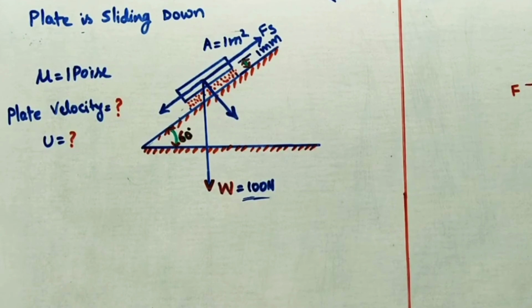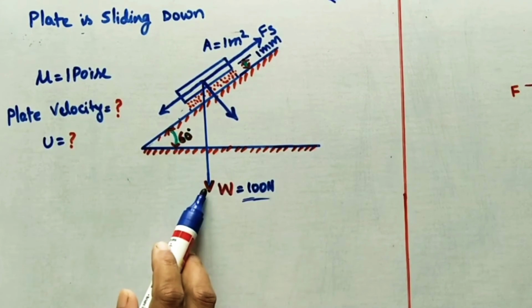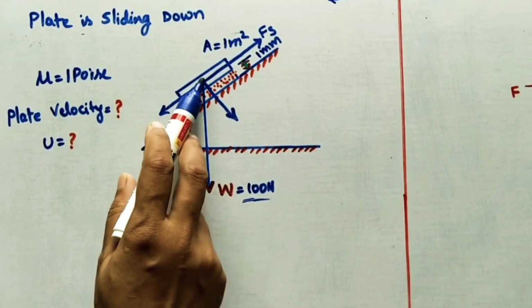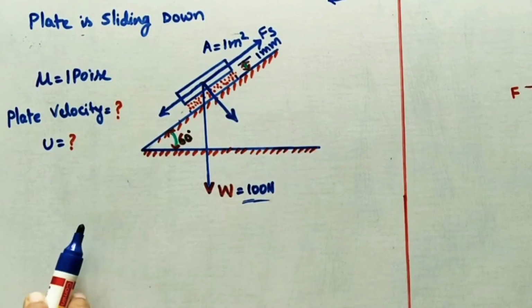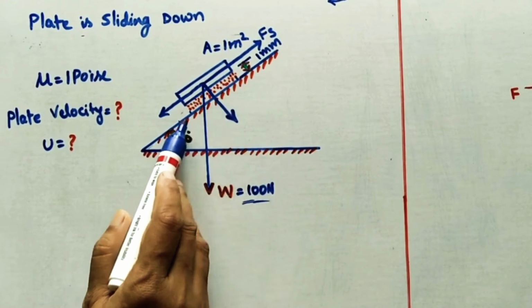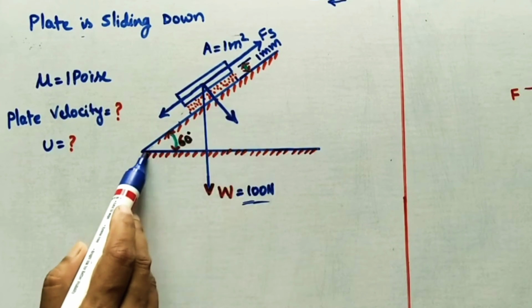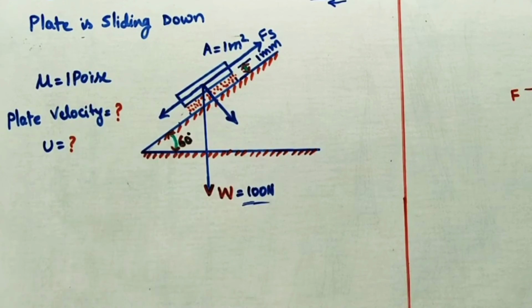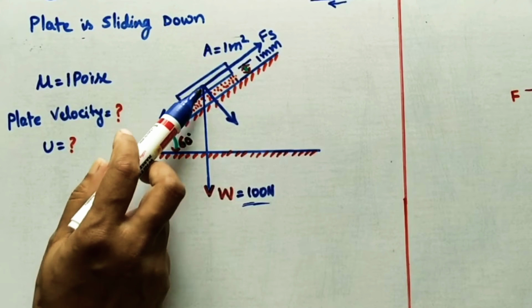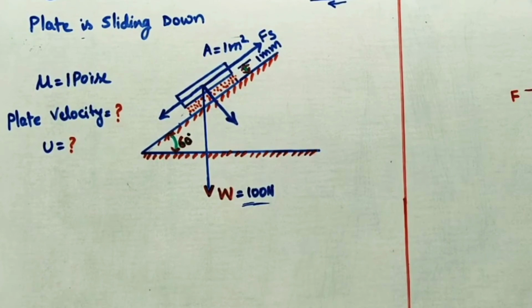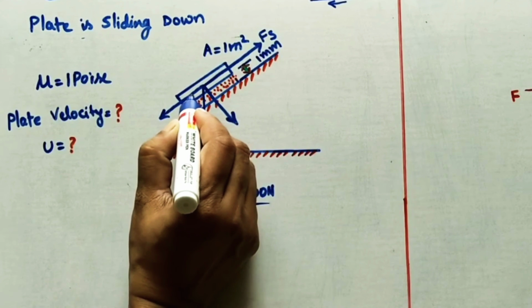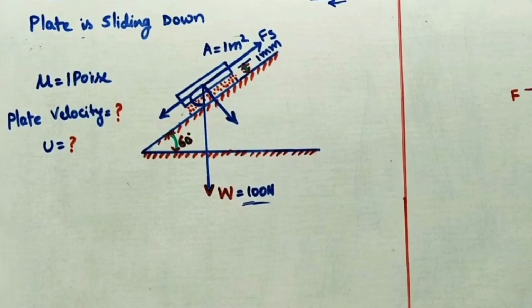So in engineering mechanics also, for an inclined force we take two components, one horizontal and one vertical. But here it is not a horizontal surface, it is making some angle. So parallel to the surface one component, perpendicular to the surface another component. Here we have to find the angle, how much angle it is making.